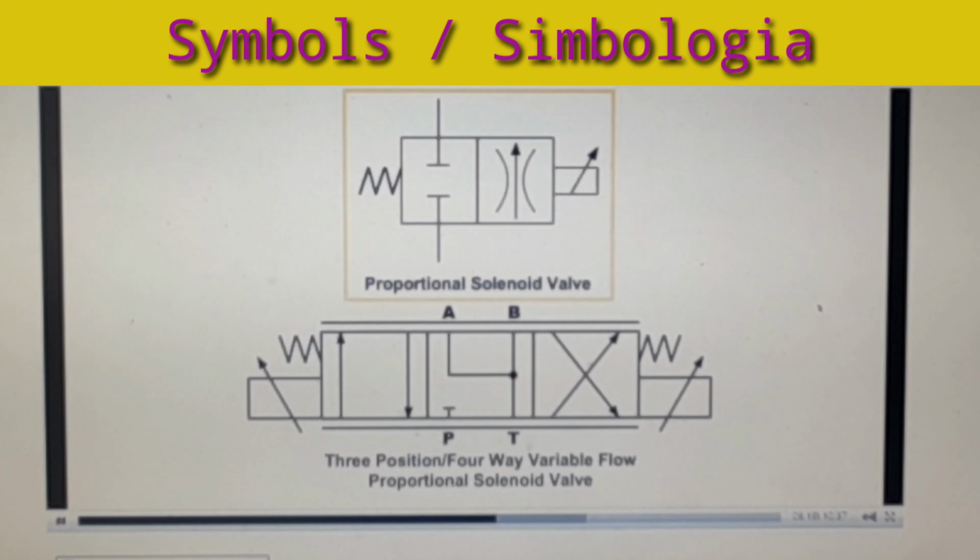A proportional valve is a variable orifice that changes size in proportion to the amperage across the solenoid. The valve is shown as a 2-position because it is closed in the spring-held position.